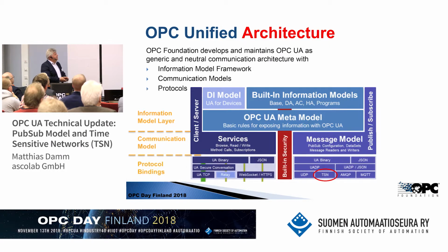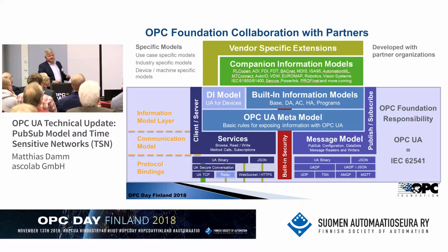And then we have protocol bindings. We always separate the communication model as a general concept from the actual protocol bindings. So protocol bindings can be added, removed, deprecated. This is the more dynamic part of OPC UA on the communication side. But the good news is you don't care about these details. That's done by the OPC Foundation. So if FDI and VDMA are talking about OPC UA, they just assume this is working and will be further developed and enhanced. This is the responsibility of the OPC Foundation.